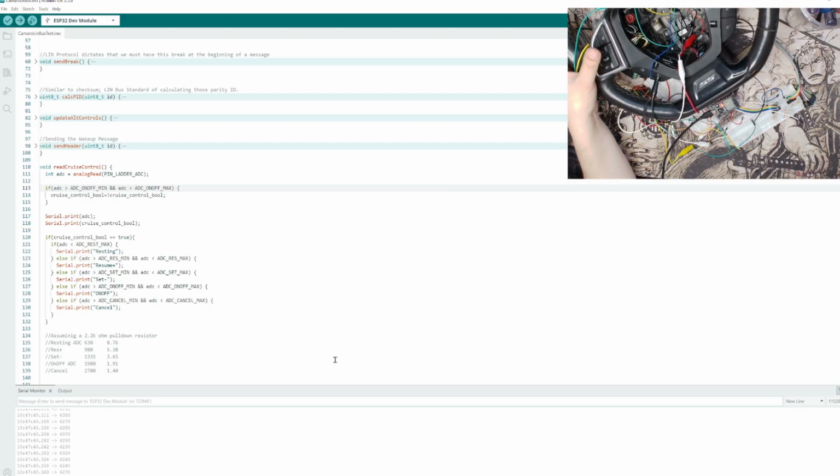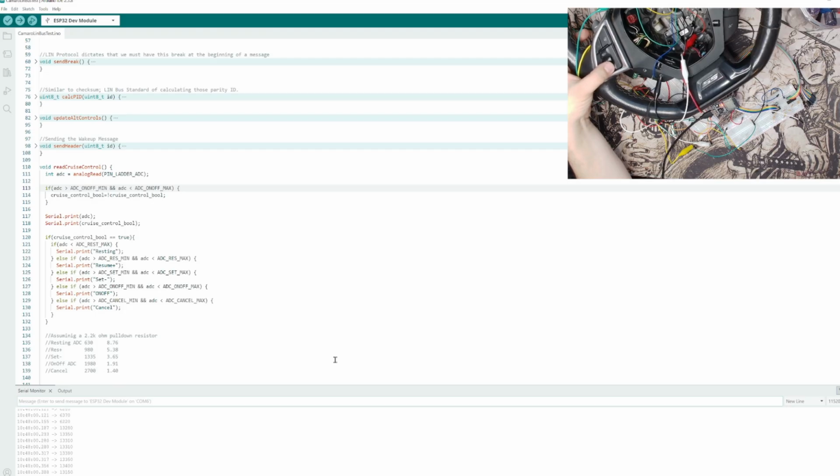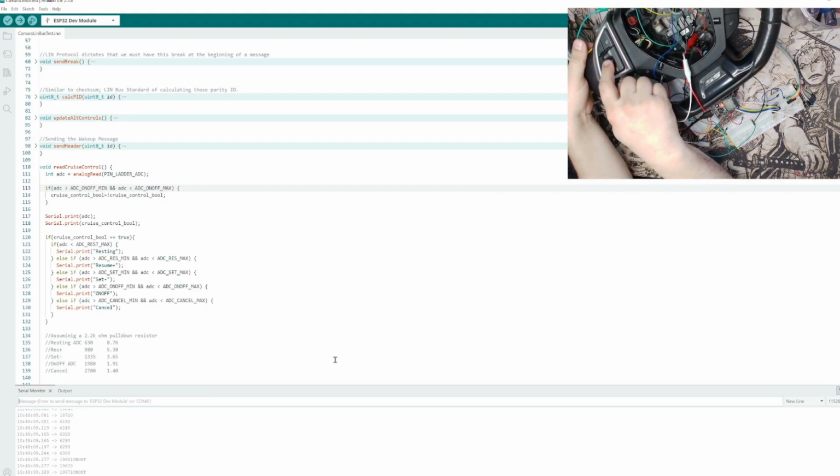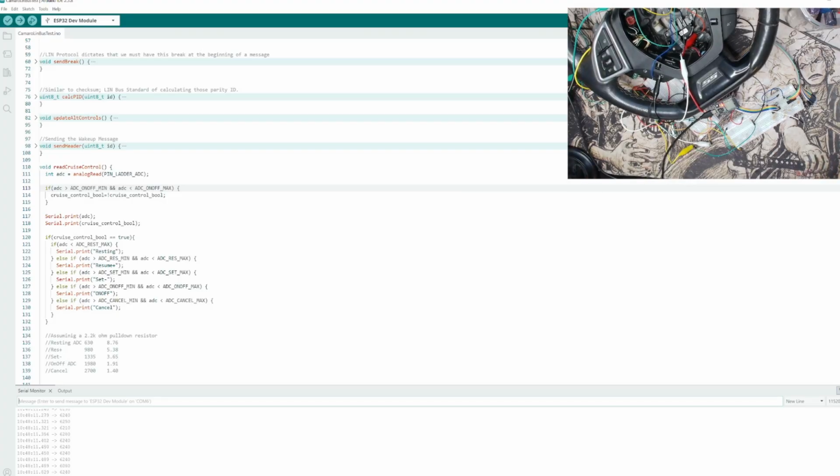So we have to add something in here. What they call it, I believe, is a debounce. And if we look here, my buttons work. When it's on and when I turn it off, it's reading an ADC, but it's not actually doing anything, right? It's not printing, which means now we have a logic that works. It only works when that's on. But we have to make sure that we're controlling this button and the sensitivity of it.